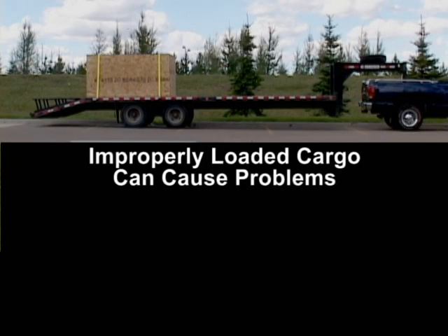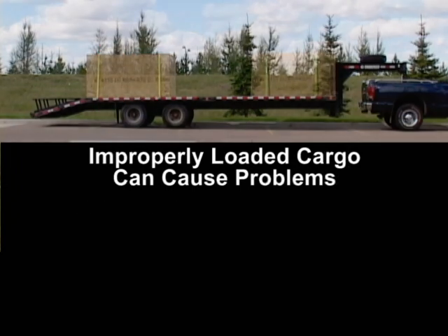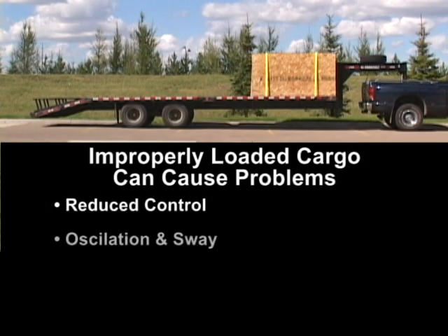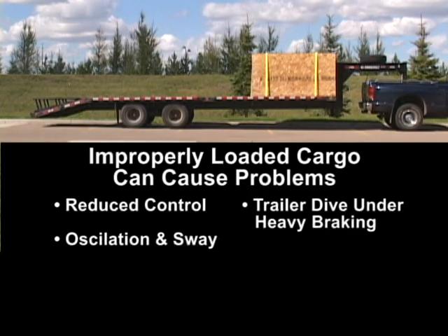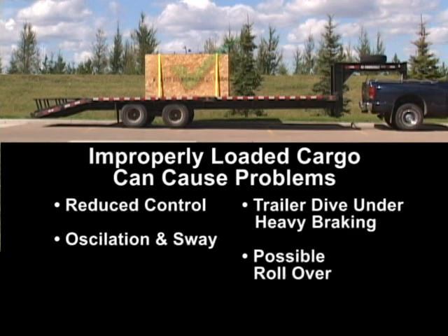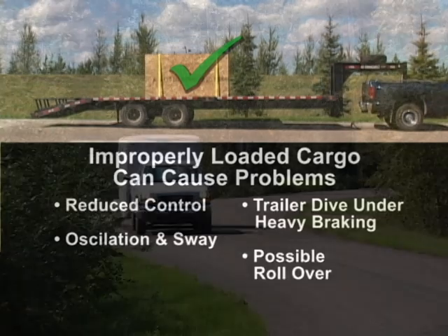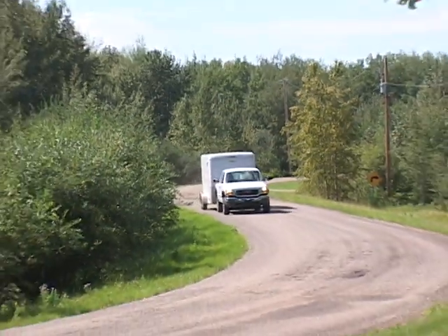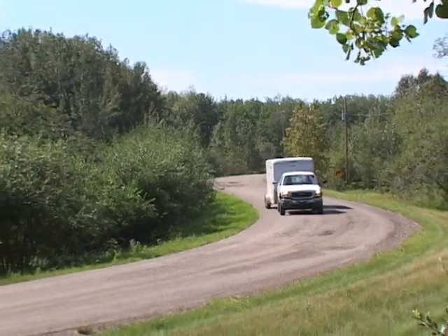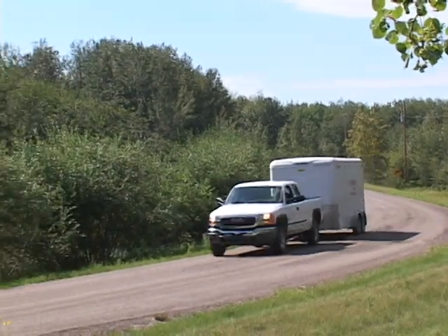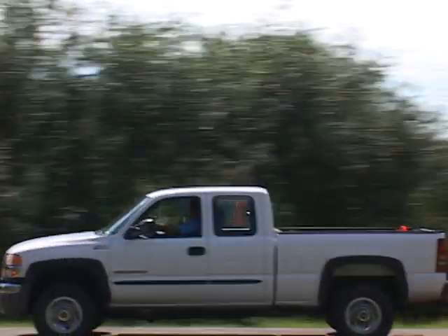Uneven or improperly loaded cargo can cause problems such as reduced control, oscillation and sway, trailer dive under heavy braking, and the possibility of a rollover. To lessen the stress on hitches and tongues, always slow down when traveling over bumpy roads, railroad crossings, or any uneven surfaces.